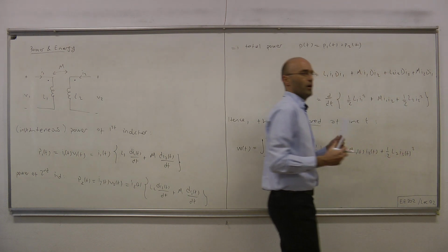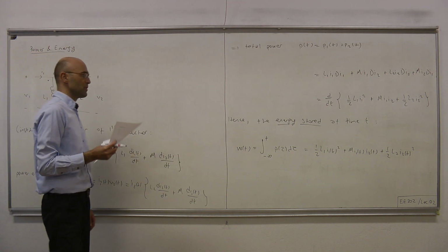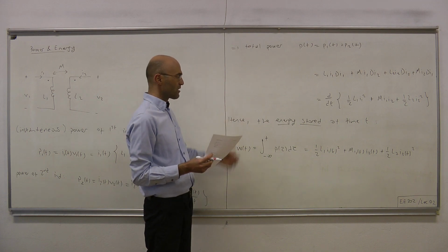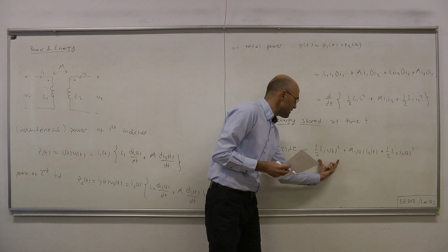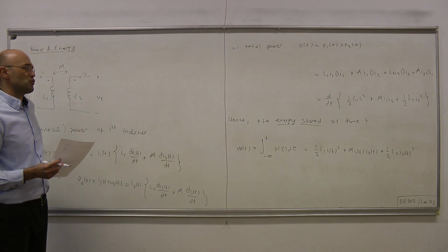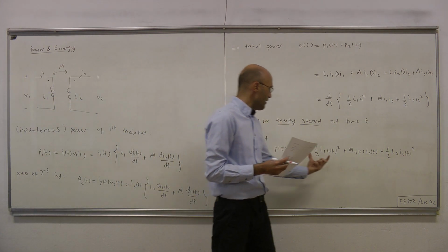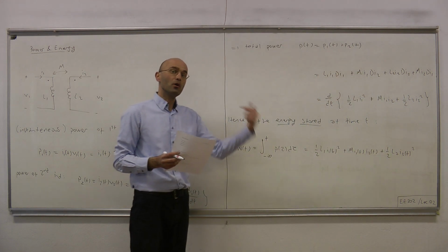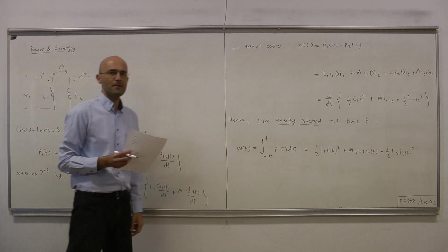Now for the usual, just a regular single inductor, for the uncoupled case, what we did have was this form, 1/2 L, the inductance times the square of the current. Now, for the coupled inductor, we have that term, we have also 1/2 L2 I2 squared term, but also we have the cross term here, n times the product of the currents.